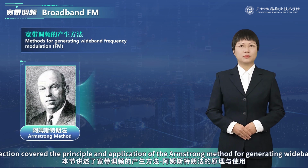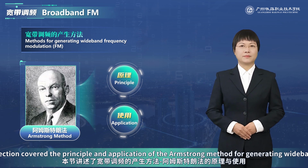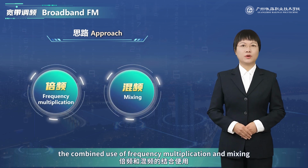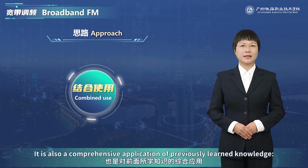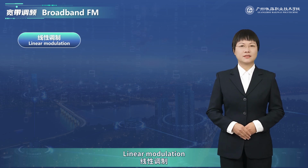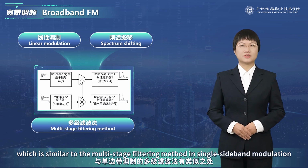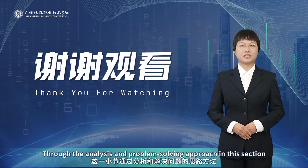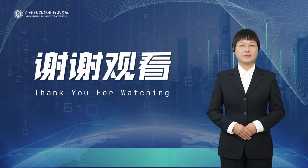This section covered the principle and application of the Armstrong method for generating wideband FM. The core problem-solving approach is the combined use of frequency multiplication and mixing. It is also a comprehensive application of previously learned knowledge, linear modulation and spectrum shifting, which is similar to the multi-stage filtering method in single sideband modulation. Through the analysis and problem-solving approach in this section, I hope students can apply it in their future work and studies. Thank you, everyone.